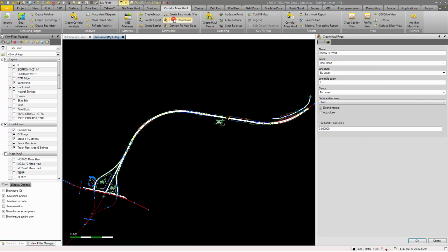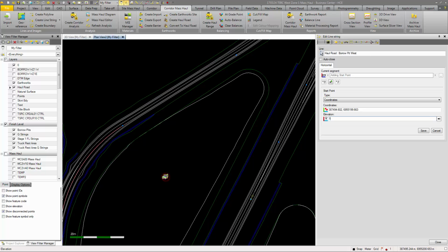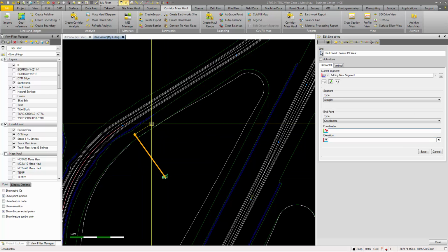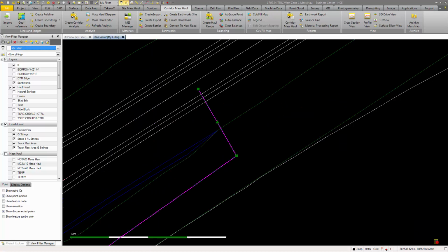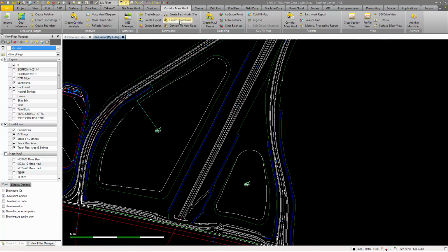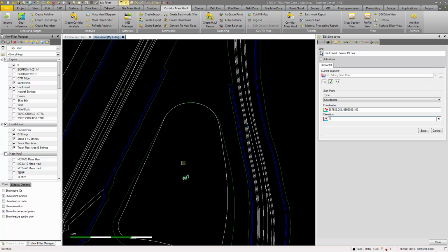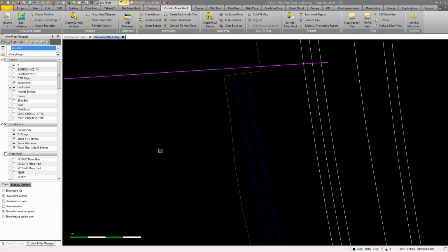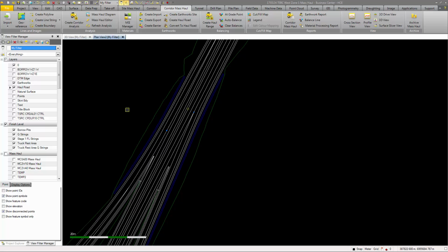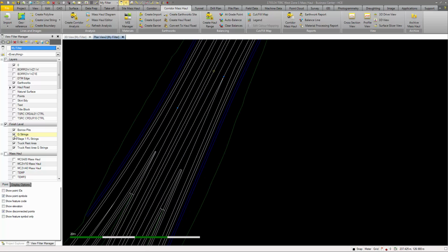Next, the haul roads were created. At this stage, we don't know the haul costs, so $1 was used for each road. We created the haul roads to intersect the alignments at a section where there was a transition between a cut and a fill. A haul road was also created to connect the on and off ramps to the corridor.